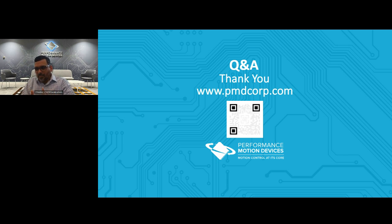So you can have a flat where you have all the drives on the main controller. The thing is you have to send update commands to each one, right? So the communication that goes between them increases. The distributed architecture is the host is talking to one, and then there's a second network that's used in the back end to talk to the slave drives. So it depends on your machine design, and we've seen both used.